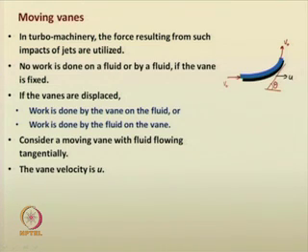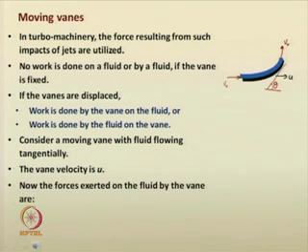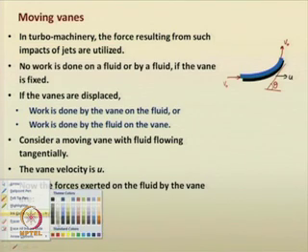So, the vane velocity is u, water is coming at a tangential velocity v 0, and it is exiting at the same velocity v 0, because we have assumed steady state conditions, right. Now, the forces exerted on the fluid by the vane, we can suggest two forces, that is, the forces exerted by the vane on the fluid, the reaction components, right. So, you can say the vane exerts a force, maybe I can give a different color now.